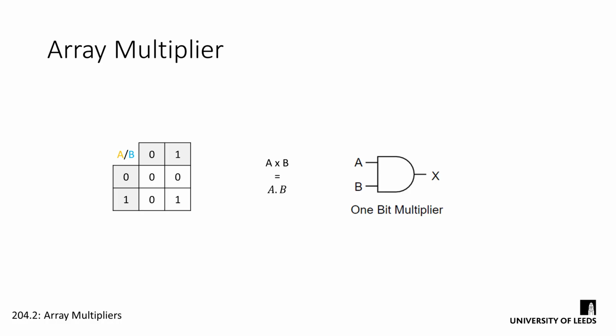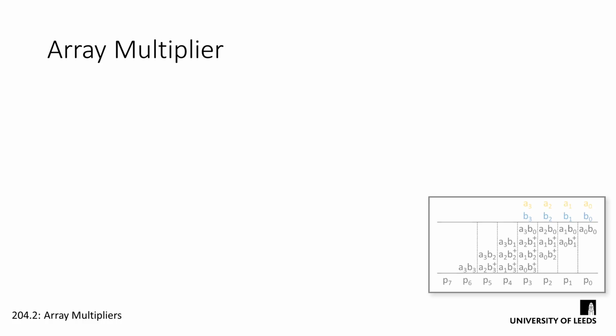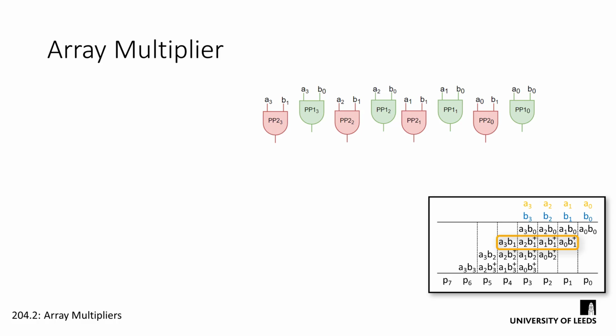With this in mind, we can start building the RTL for our array multiplier. We'll do this by constructing each partial product in turn. As we've seen, to multiply two single bits together, we just AND them. So we'll look at our general model and create some AND gates to generate the first partial products. When we generate our second, we'll physically left shift it in our RTL diagram. This will help us when it comes to adding the bits up. I'll also add in some columns to keep everything in line.